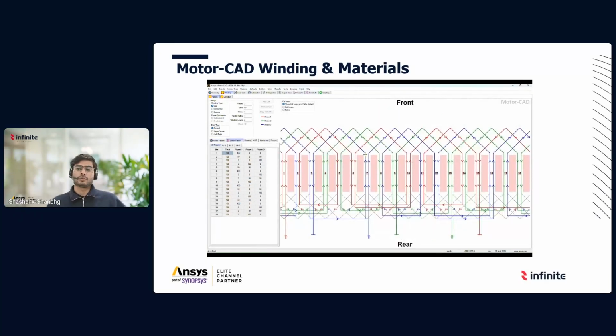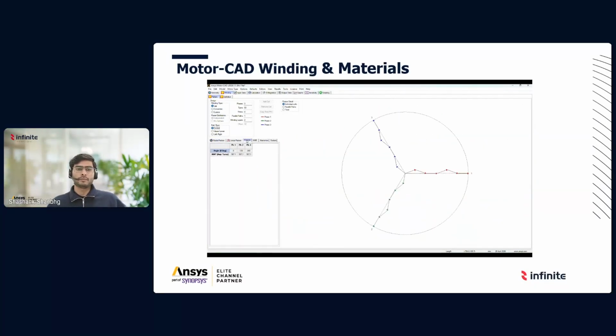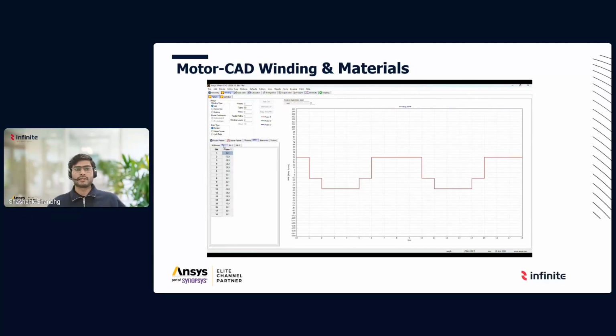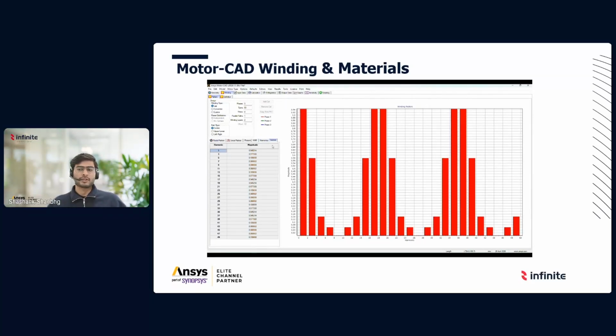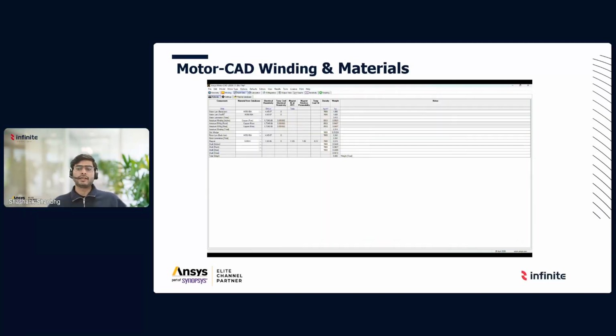You can also visualize the different coil loops and see the phasors. You can visualize the magnetomotive force and the harmonics, in terms of either mechanical or electrical frequency. We can also see the fundamental winding factor, as it is directly proportional to the torque of the machine.